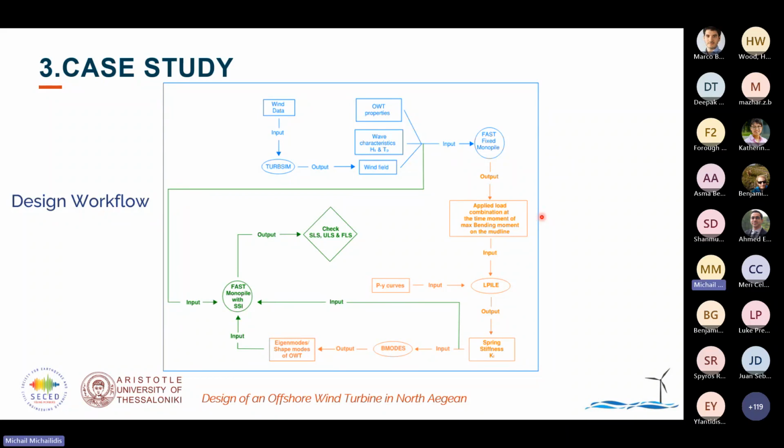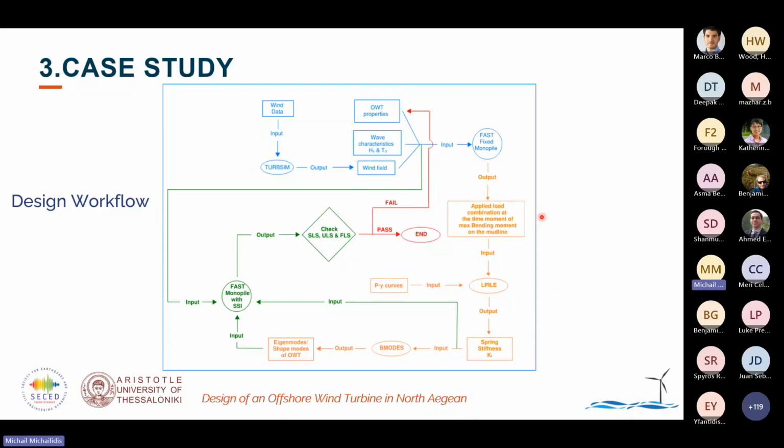Once we conduct the analysis again, we can check our structure against the serviceability, strength and fatigue checks that we need to have. If everything is fine with our checks, then the design is complete. Otherwise, we need to return to the selection of the eigenmode characteristics and the offshore wind turbine properties, and repeat the process.